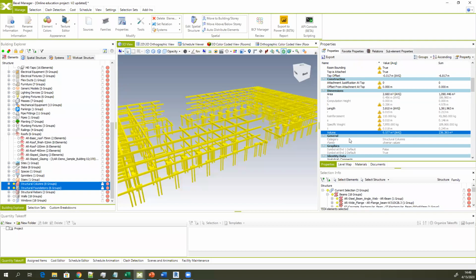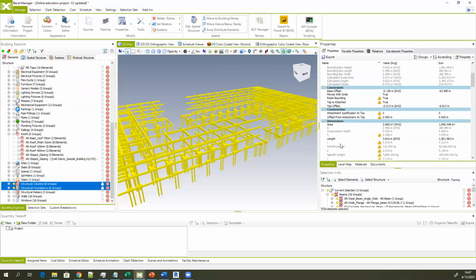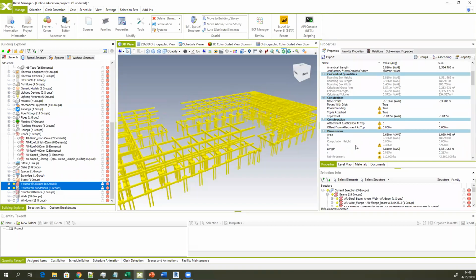So this grouping is available from the authoring tool, or an additional way you can group the properties is if you export IFC using specific mapping options, then you can map and group your types or groups of your properties according to your needs or specific requirements, and these will be grouped accordingly. This is not something that the Bexel Manager does by itself. This information is read from the available information coming from the imported BIM model.